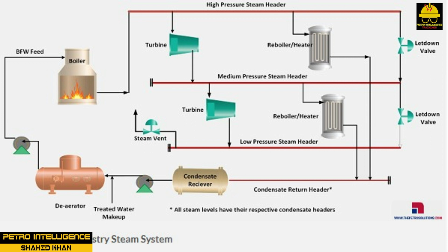Non-condensing operations utilize the exhaust steam in operations where lower pressures are required. MP steam is supplied partially by exhaust from small back pressure turbines and extraction steam from larger turbines. In case of insufficient supply from the above sources, the letdown station between the HP and MP headers makes up the balance of steam required at the MP header.